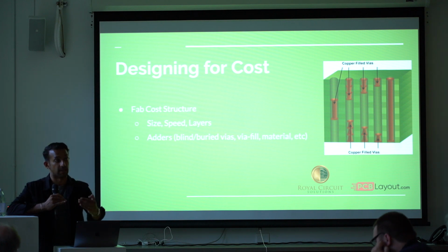However, assembly is the exact opposite. With assembly, as you order more boards, the unit cost will actually go up. And the reason for that is it's done on an individual unit scale, on a linear basis. I have to run each of those through the pick and place. Now, pick and place, you put them in arrays, fine, that's not a huge deal.